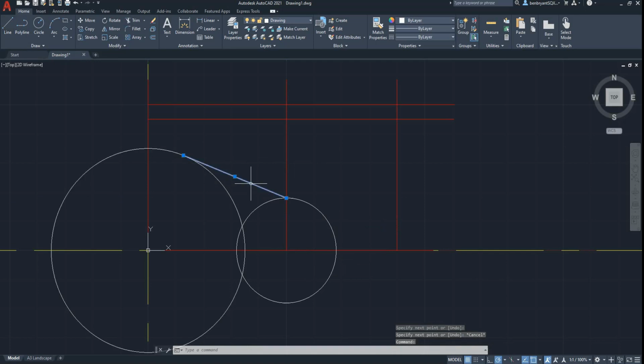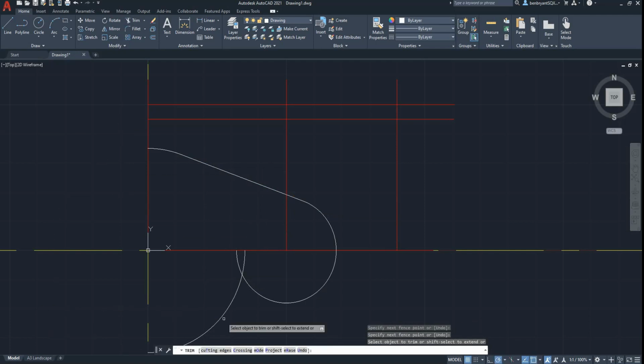It's the same as what we did last time. Then pick it up on the corner and stretch it to the other tangent, like so. Now I've got a tangent to tangent snap, and essentially just trim out everything that we don't need. That's all internally. Remember to trim off the little edge, and then externally as well, like so. That just leaves us with that little flick.